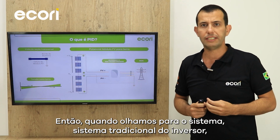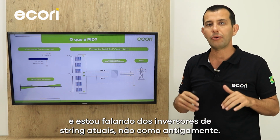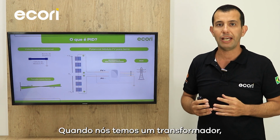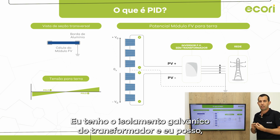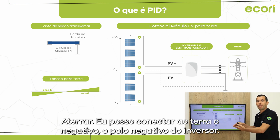So when we look at the traditional system of inverter, and I'm talking about current string inverters, not the past. In the past, we used to have transformer-based inverters. When we have a transformer, we don't have these problems because we can separate between the input and the output. I have the galvanic isolation of the transformer, and I can connect to earth the minus, the negative pole of the inverter.